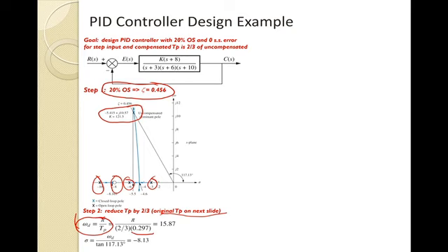So again, going back into our complex plane here, if we have our dominant pole here, remember that this is our j-axis, and this term right here we often call sigma, and that's going to be negative zeta omega n. So when you see sigma, like you do on that slide, that's this relationship on the real axis, and then this term right here we call omega d, which again was our natural frequency times the square root of 1 minus zeta squared. Okay, so these are the two terms, sigma and omega d, relative to where we are with our dominant pole.